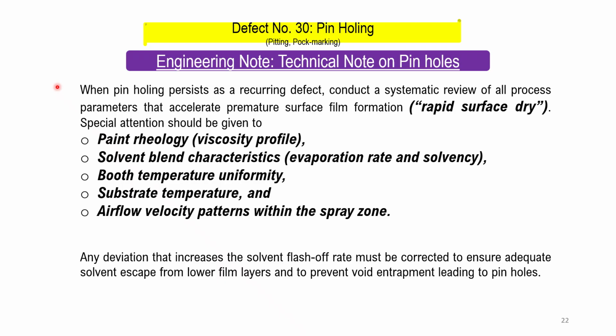Special attention should be given to paint rheology, that is, viscosity profile, solvent blend characteristics, that is, evaporation rate and solvency, booth temperature uniformity, substrate temperature, and airflow velocity patterns within the spray zone.